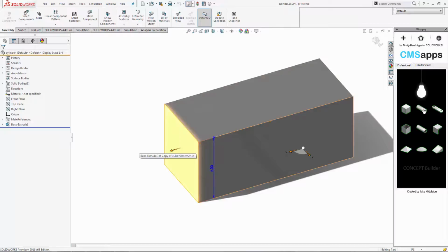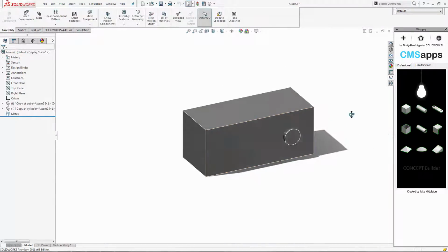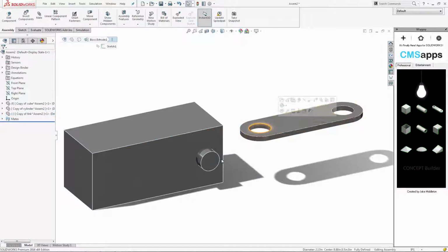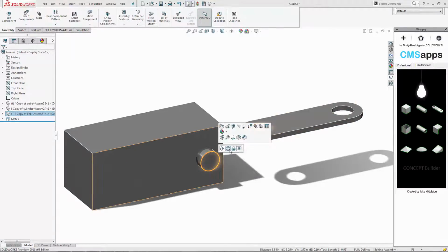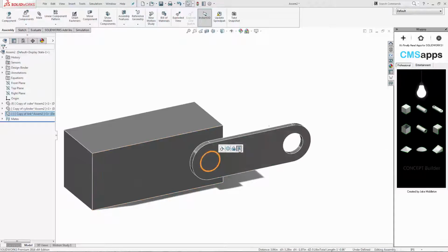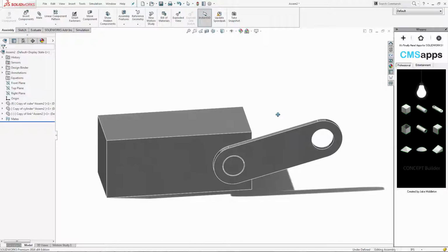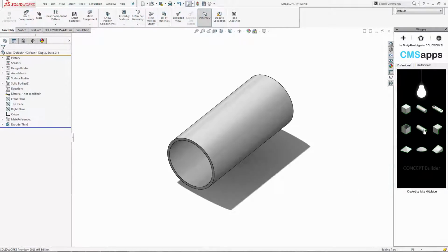So the app is pretty neat. It's very simple but very, very useful. You basically click on the primitive shape that you want, if it's a cube or cylinder or link, and then you position it around, and you can use instant 3D to size it. Don't forget to hold down the control key to add the quick mates in here. Like profile center is great for making links go together. So you can basically go and hook these up any way you want.